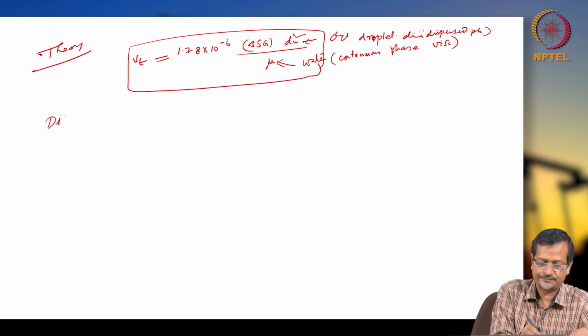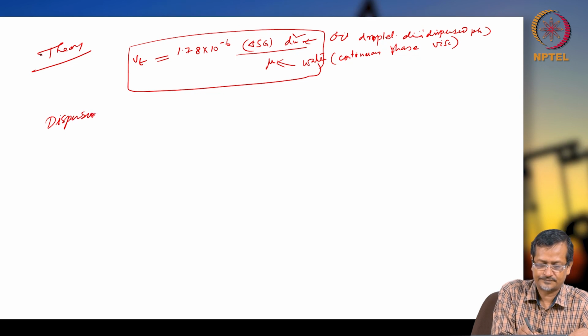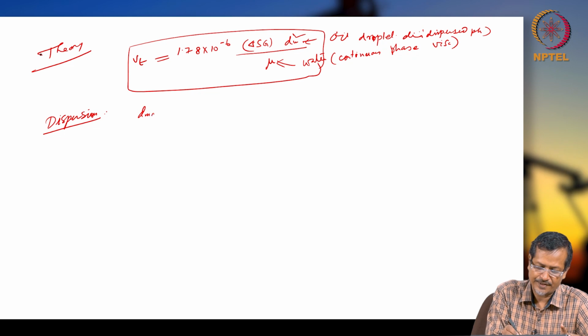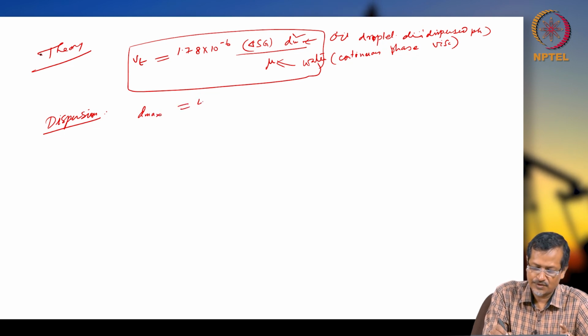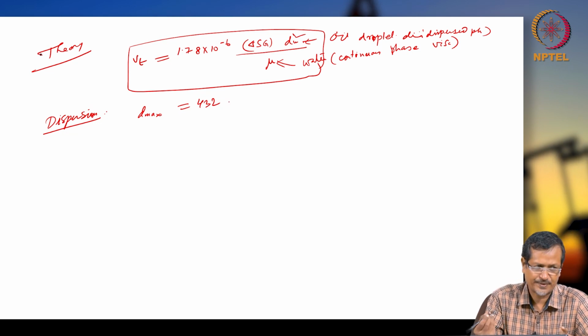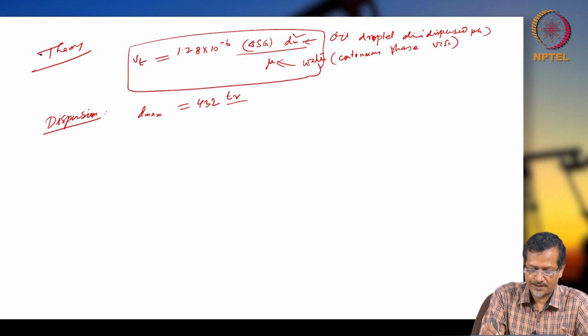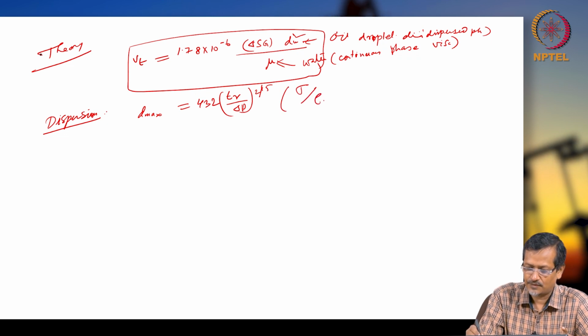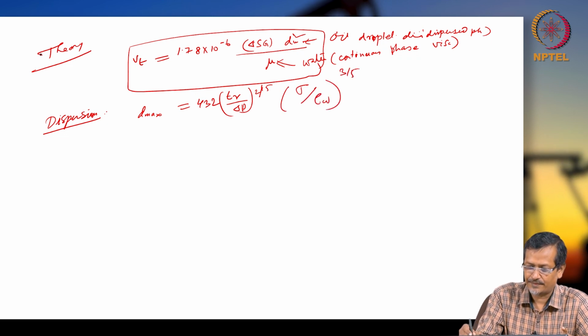And dispersion. So they have given one d max formula, dispersion formula 4.32. There is no derivation here, they have given just an empirical type formula. d max equals 215 times Tr, del P to the power of minus 2 divided by 5, sigma, rho W to the power of 3 divided by 5.